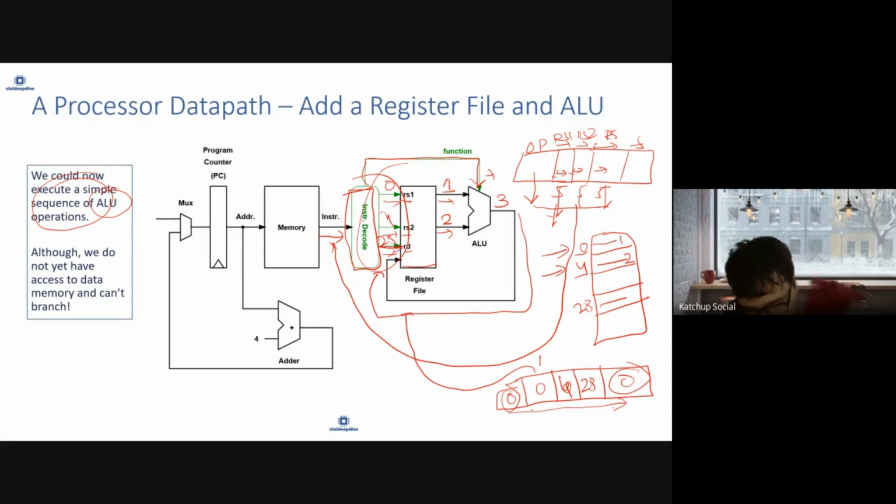Read address is given here. So at address 28, value 3, which is the output of the addition, will be stored. So this is how your program counter and then your ALU function, which first decodes the instruction, accesses the value of the instruction data from the register file, and that's why the register file is closest to the CPU.